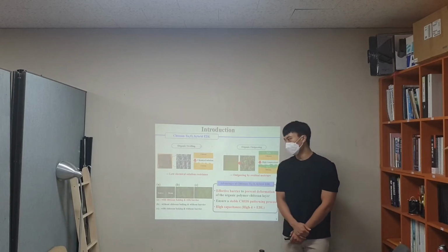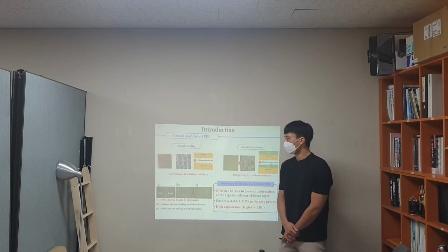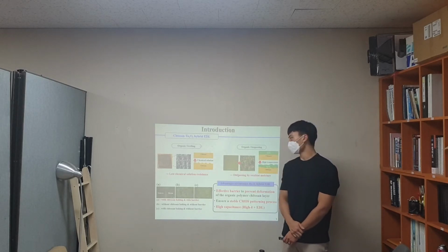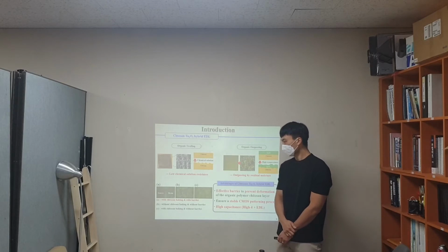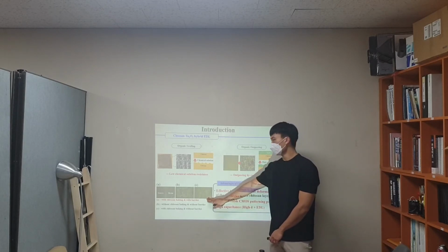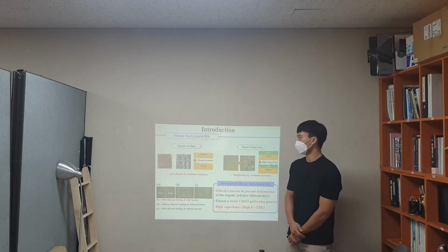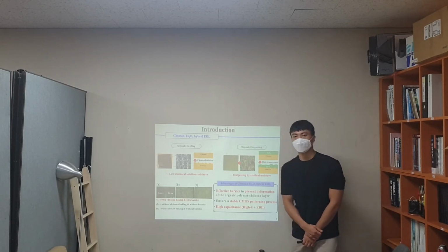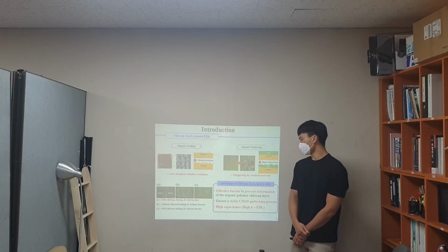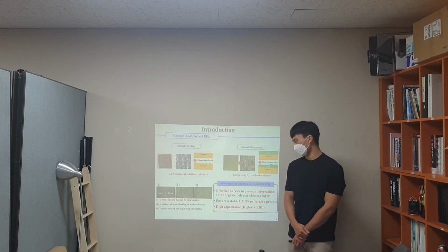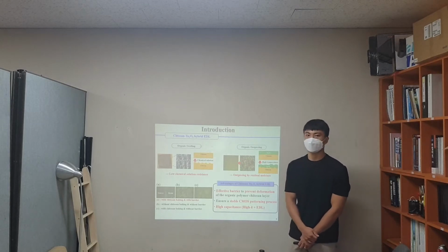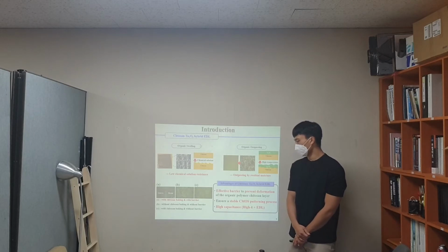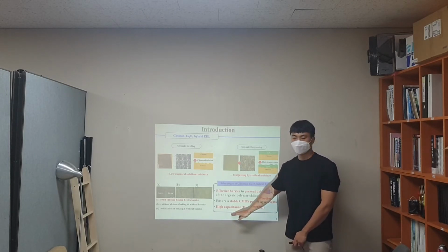The electric double layer without tantalum oxide undergoes swelling or outgassing problems during the baking or photolithography process. But the EDL with tantalum oxide was well prepared without outgassing or swelling problems. Accordingly, tantalum oxide acts as an effective barrier to prevent deformation of the organic layer, and it ensures a stable CMOS patterning process. Also, tantalum oxide is a high-K dielectric, so its capacitance is high.